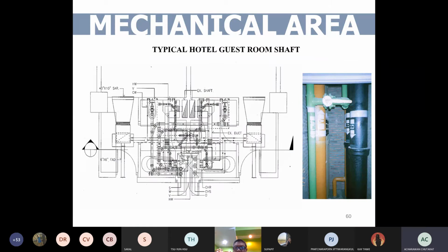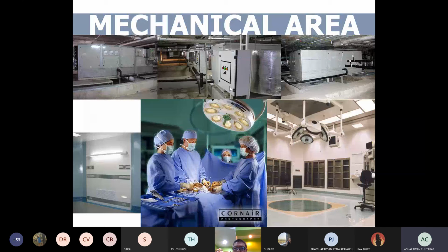Can you explain the laminar flow again? You mentioned laminar. The flow that we use in the OR needs a special diffuser. In the operation theater, they have to put a diffuser which can distribute the air from the top very slowly, to make sure that the air pattern is laminar, not turbulent.